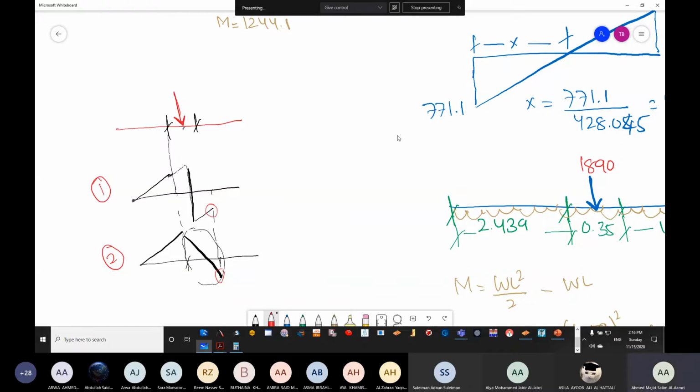Okay, so we'll not spend a lot of time. Now, in this particular theory, which is theory number one, you are assuming that the column is acting at the center point only. This is only for the simplification of the bending moment diagram. Now, when it comes to reality, the loading will not be located at the center of the column. You will see that the loading is actually distributed along the column. Do you agree?